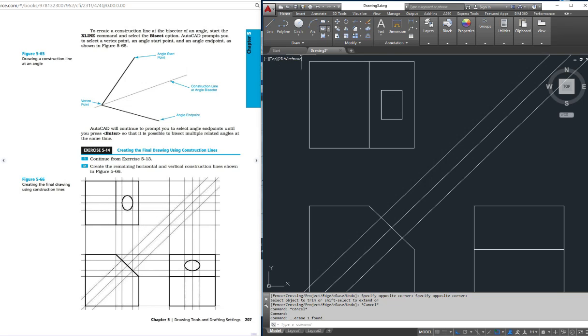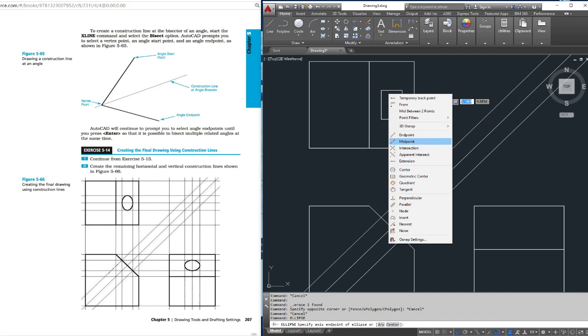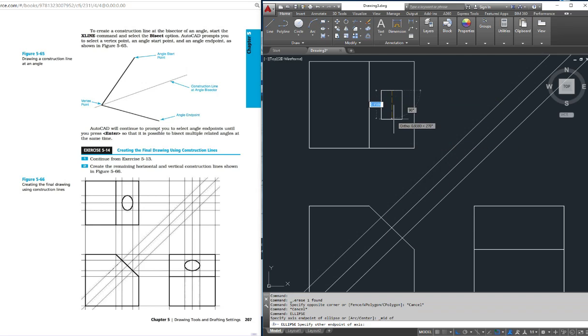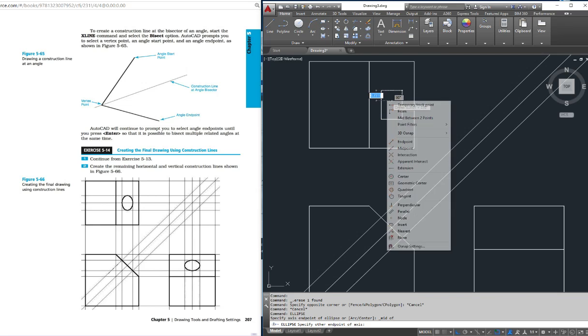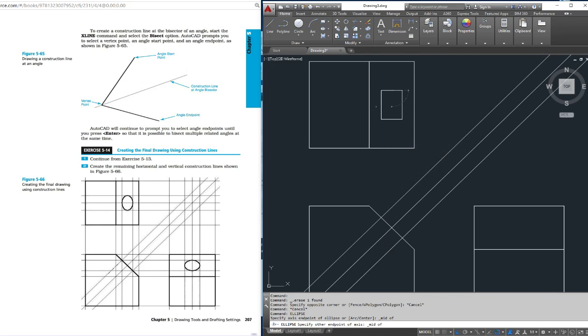So now they want us to add this ellipse right here. So I could use the tool in the ribbon, there's the ellipse command. Or you can just type ellipse. Now with the ellipse, you need to pick a cross. So I need to pick from the midpoint here and then pick a cross. As long as you pick across the rectangle first, it'll work out. If I screw it up and I pick here, now my ellipse doesn't make any sense.